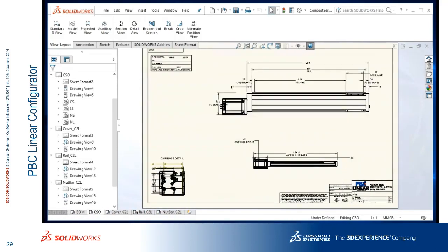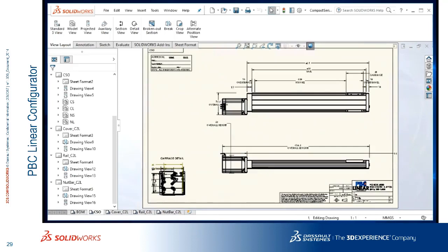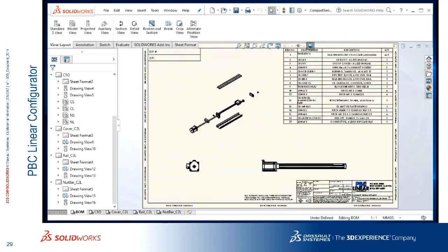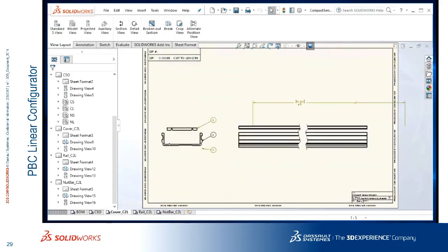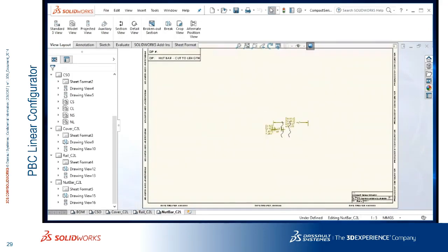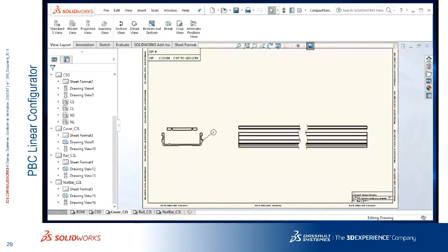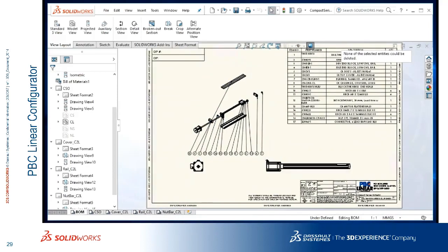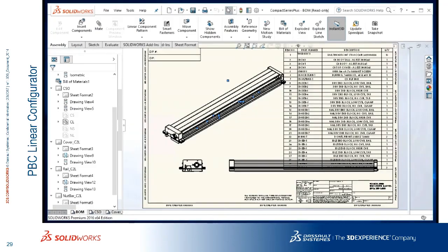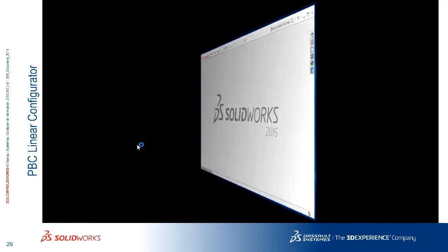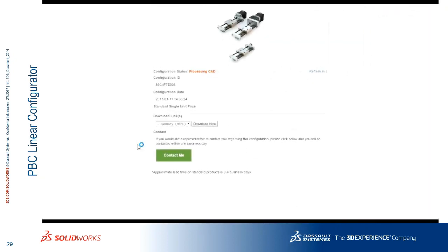You can see there it just threw everything away, but it's going to go ahead and reformat and bring everything back in position of where it needs to be. Occasionally you get a dangling dimension in there because, well, you dimensioned it to this geometry, but they choose not to have that part. So my routine will go through, delete out all of those features that they don't want, and it'll give them a finished print at the end. You saw it auto-ballooned it right there. So that'll be for the production print of how they actually put it together. So literally, it'll do everything for us.